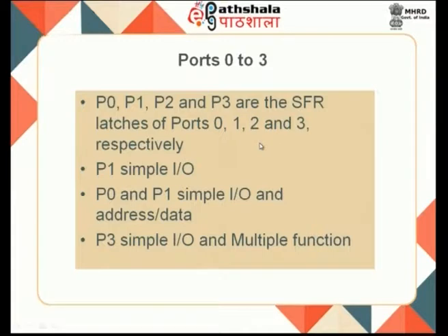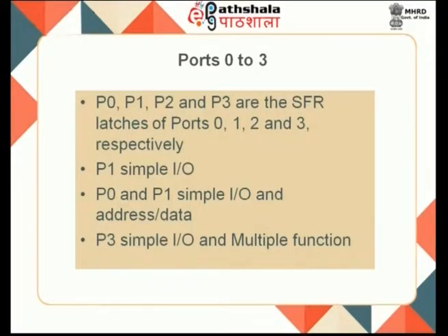Now, we will be having ports. We have four parallel ports and 2 serial communication ports. These parallel ports can be used for reading data or sending data out, or reading data from outside, or you want to send an address to a memory, or read data from your memory, or send it to an output device or read it from an input device. All those things can be interfaced through these ports. So, P0 to P3, we have 4 parallel ports.